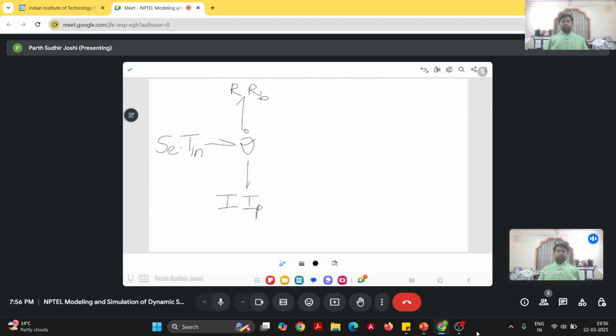And then for the rotary to translatory motion change, we can use a transformer element to represent that. The conversion factor is V equal to R into omega, so the transformer modulus will be R. And then the rotary energy is being transferred to the rack.